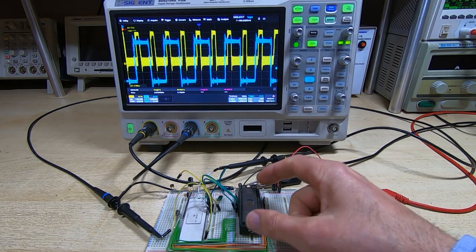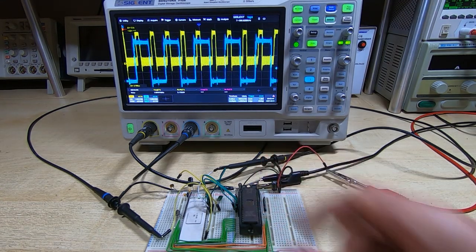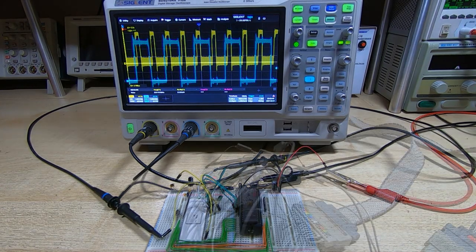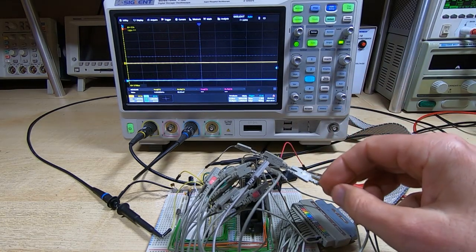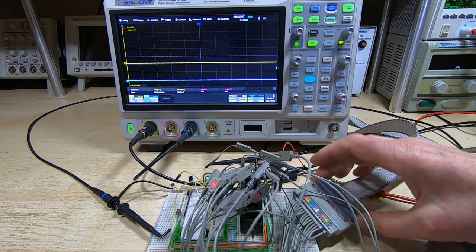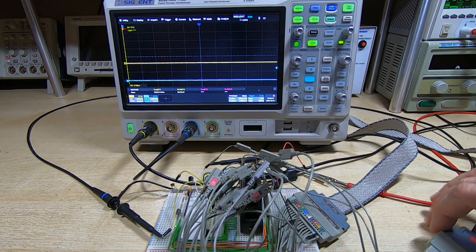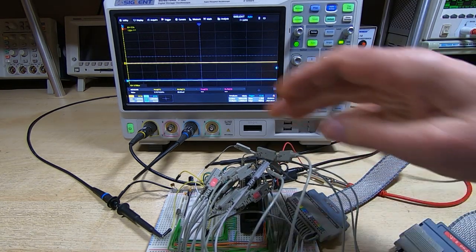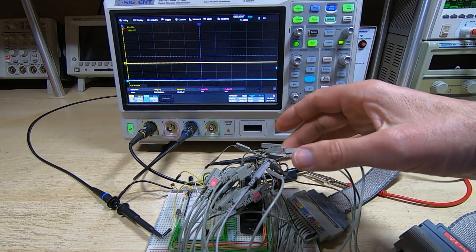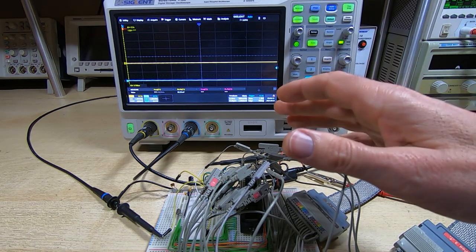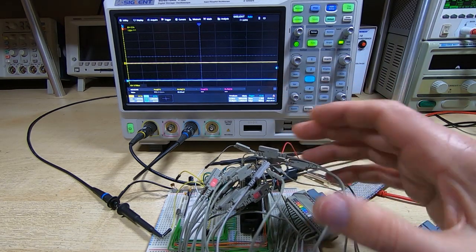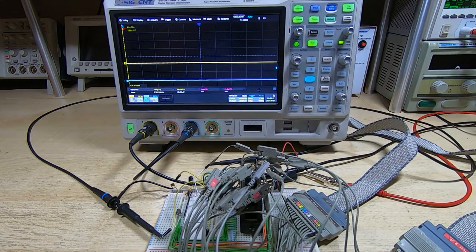So what we'll do now is we'll hook up the logic analyzer and see how we can start using that to analyze a system like this. Okay, I've got the logic analyzer hooked up to the basic signals. Pod 1 is hooked up to the data bus, and pod 2 is hooked up to the address lines. As I said, I'm only currently using 3 address lines. We'll add more as we need them. And so what we'll do now is I'll move the camera so we can see the logic analyzer, and we'll get that set up to look at these basic signals.